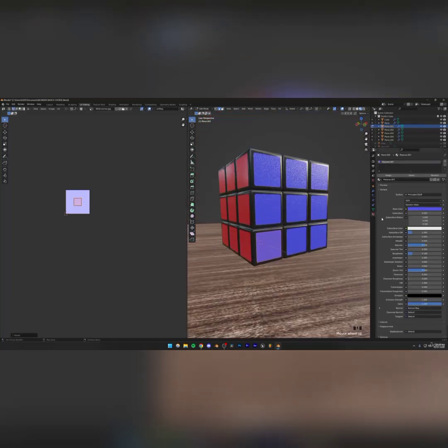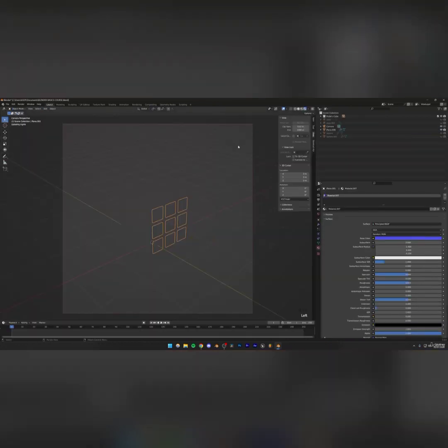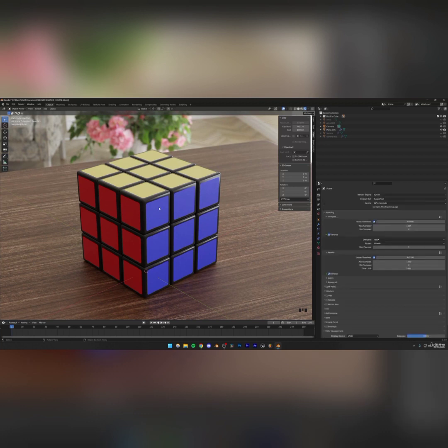And we can also go ahead and increase the roughness slightly, because I think this is a lot more realistic. And then we can just go ahead and adjust the size. I think something like that should be good. Let's see how it looks in our final rendered view. Let's wait for it to render. Right now it is looking very fake because it is not rendered completely. Let's render it a little bit and then we'll see how it is looking. All right, so I think this looks really nice now. I think the normal map is really adding a lot.